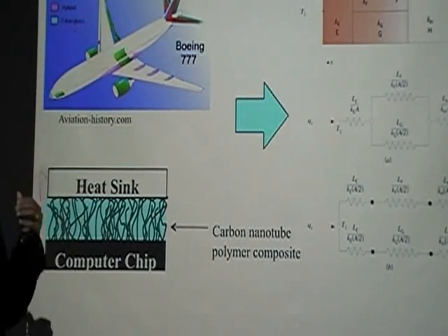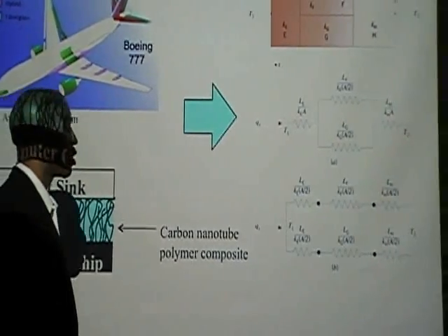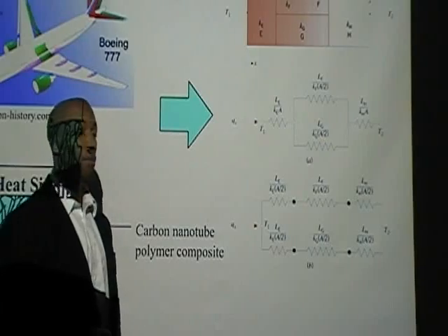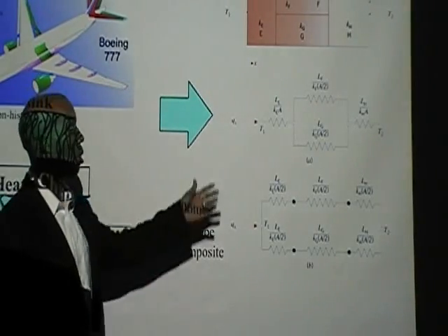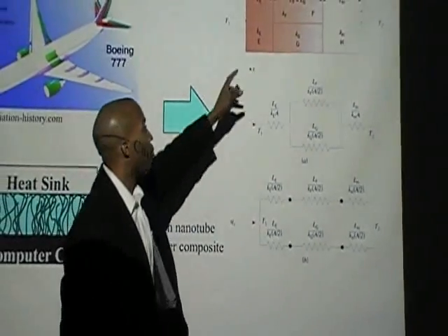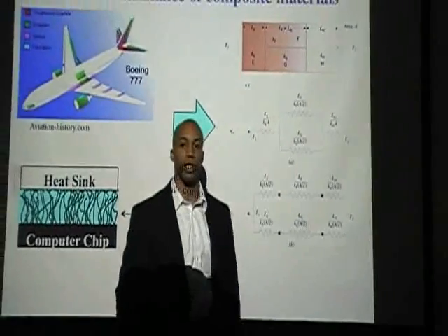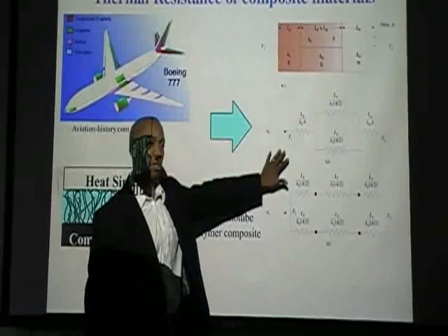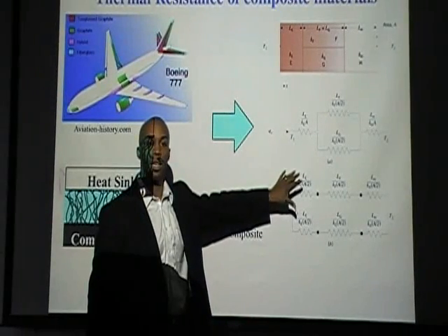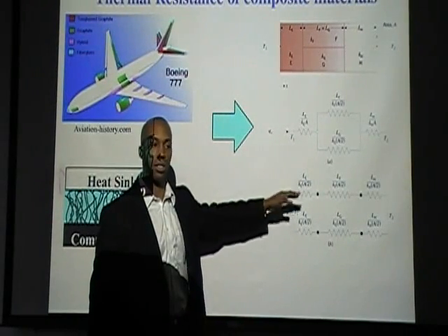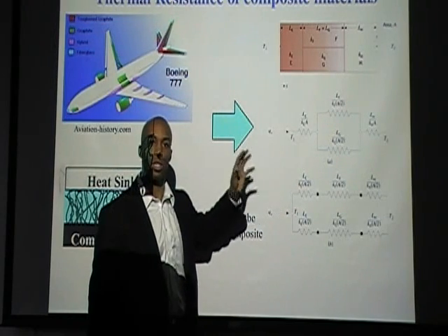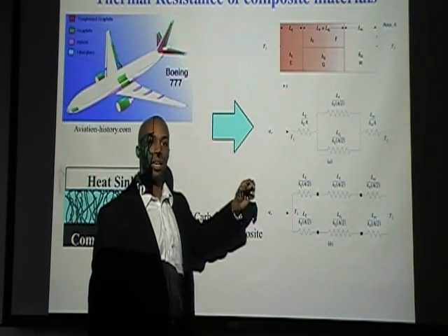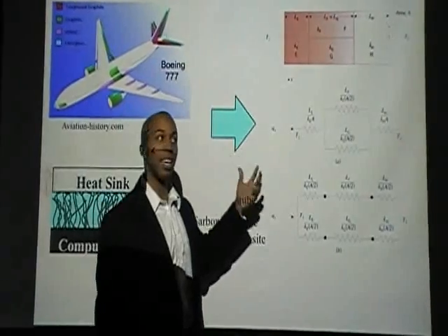Here's a cartoon from your book that shows an example of a composite wall where we have 1, 2, 3, 4 sections. There are two different ways that the book shows you can represent a circuit network, and there's some latitude afforded to engineers when using this analysis technique to set up the problem.